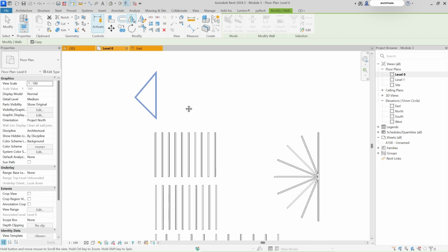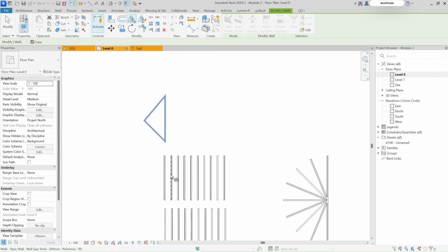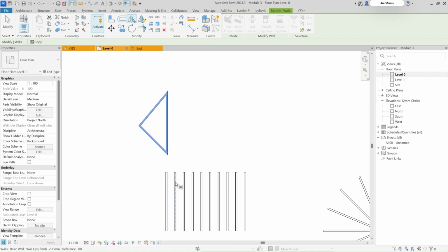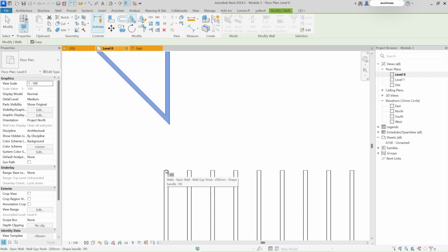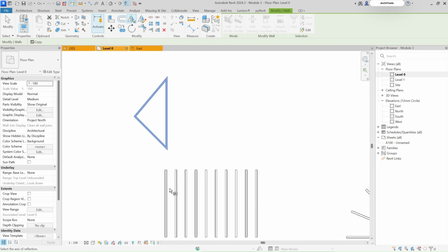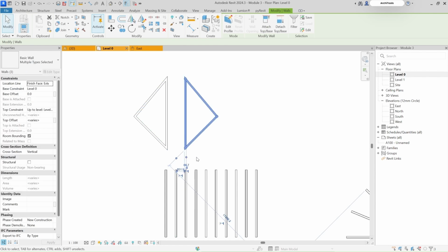If you have an axis, this option is better. So let's say this is my axis in between, and you can imagine a line that is going upwards. So this is a parallel line. You can also select any line like this also. It will mirror according to that. So for simplicity, I'll choose this line just once, and it will mirror it.